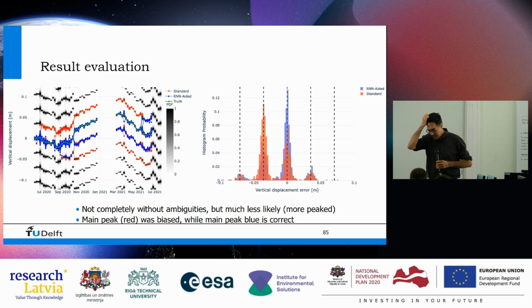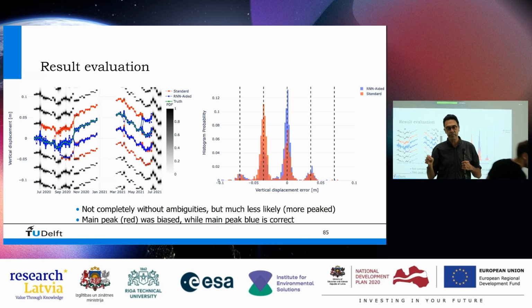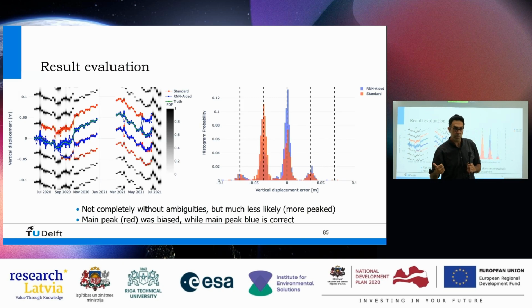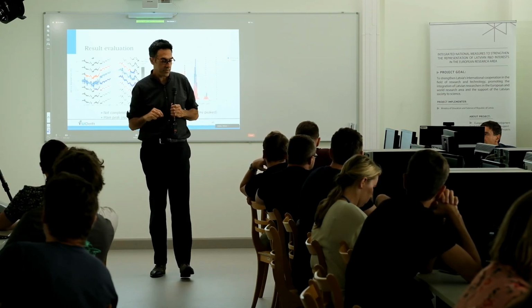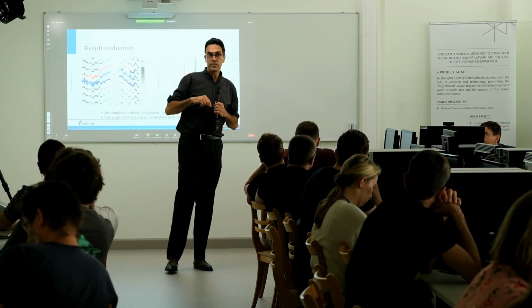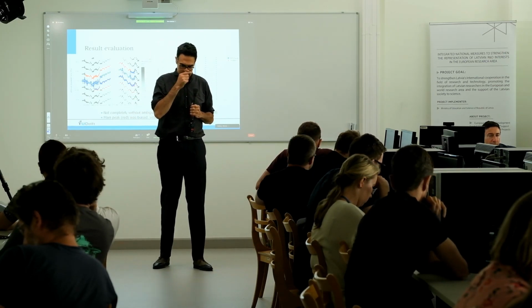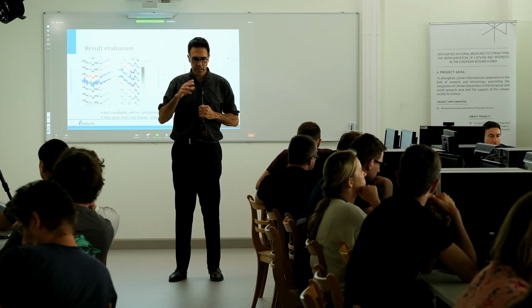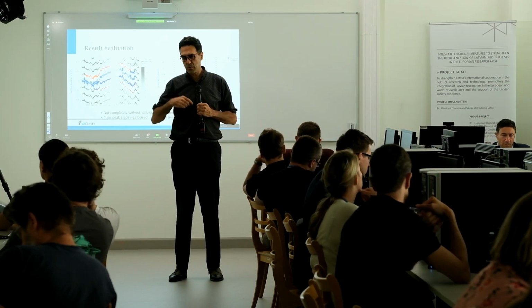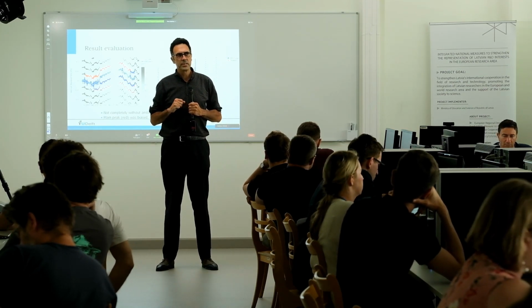So what I tried to do today was to give you an overview of InSAR, how it works. We start all the way in the beginning with this intuitive feel of the sensitivity to topography on the interferograms, why it is that we can measure deformation 1,000 times better than topography or elevation. We also looked at the different processing steps, how to get there, and at the precision levels of the observations. We looked at what influences that precision, so not only the temporal variation of the area, but also atmosphere and the orbits, all these things we talked about.